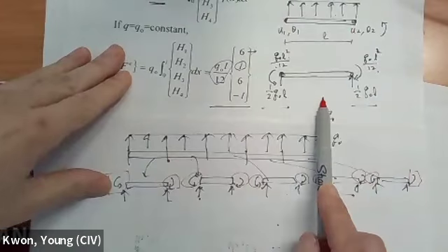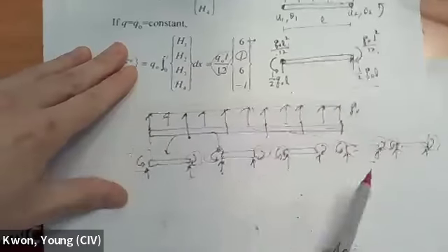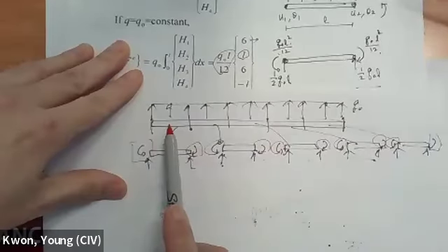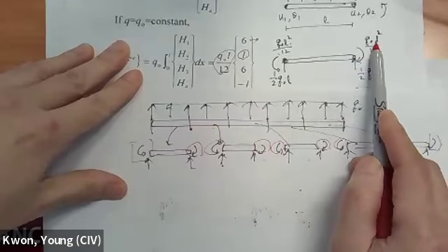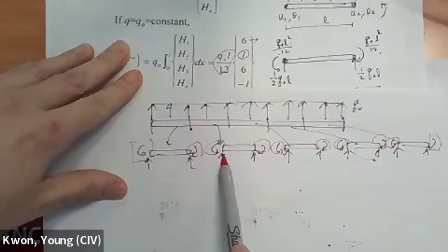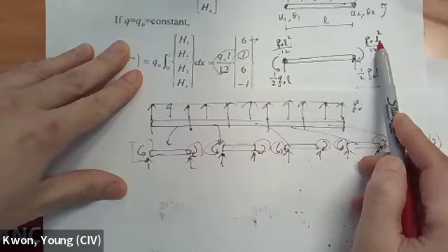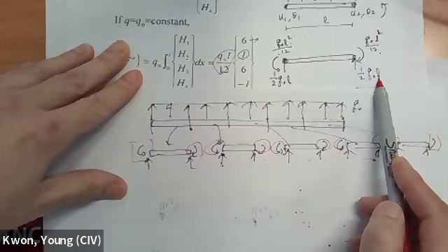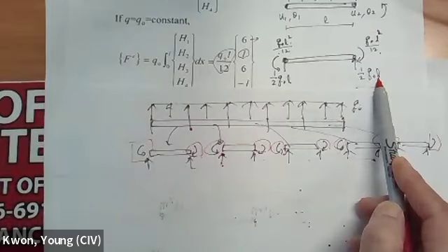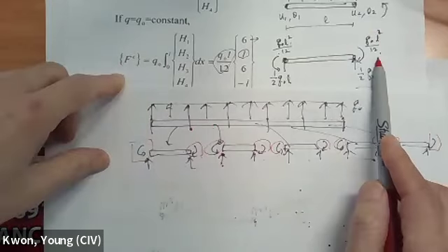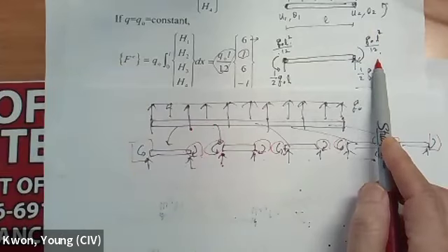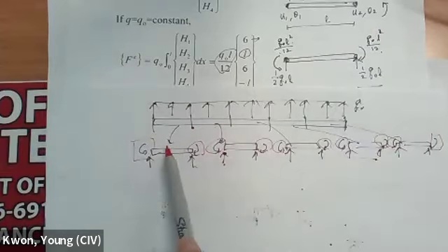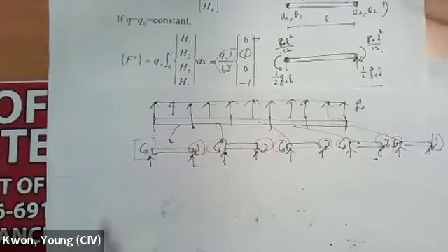Correct? Of course, in this case, the element size is not the same. So this element length is a little different from that one. Then this value, because L is different, may not cancel out each other, right? But still, that's going to be second order compared to the first order of the force, so when L becomes smaller and smaller, that's going to be ignored. So when you define the mesh, those moment effects are going to be ignored. Eventually, you have only the effect of the force.